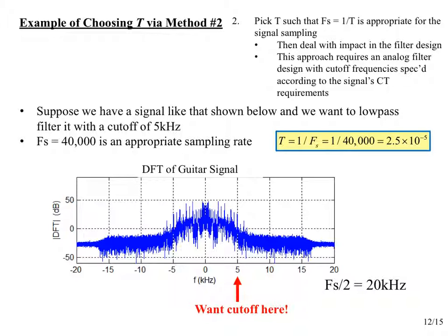for the actual signal. So it's more like comparing the signal and the filter in the analog domain, and then mapping everything to the discrete domain. Whereas method number 1 is more like taking the signal separately, taking the filter separately, and then mapping them so that they both match our goal in the discrete time world. Everything works out exactly the same way. It's just 2 different ways of thinking about it.